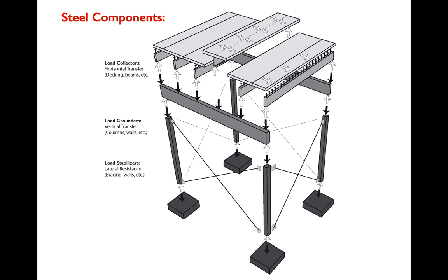And finally, we'll see them in load stabilizers too. Cross bracing especially, but also steel elements that go between columns and girders to make particularly rigid moment connections that allow us to stabilize a steel frame without resorting to big panels of walls or cross bracing.